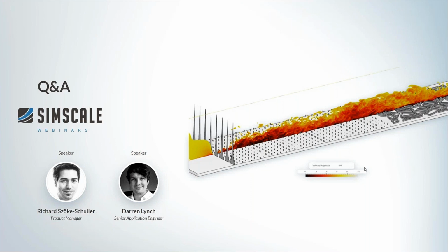So in this case, you will have a mean velocity inlet and a mean turbulence and turbulent dissipation with height. You would not have the actual fluctuations directly in the inlet yet. For that, you would need to model the roughness elements as it's done in the wind tunnel for now. So maybe that's something we can already talk about.